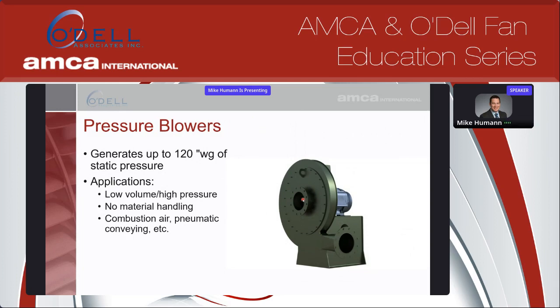These are all for pressure. You can see that the inlet and outlet is very small compared to the diameter of the actual wheel. Typically, we're not looking to handle material with these. That's not really what they're designed for. You see them in a lot of combustion air applications, some pneumatic conveying. So we're looking at pressures up to about 120 inches here, with what we would call a pressure blower.